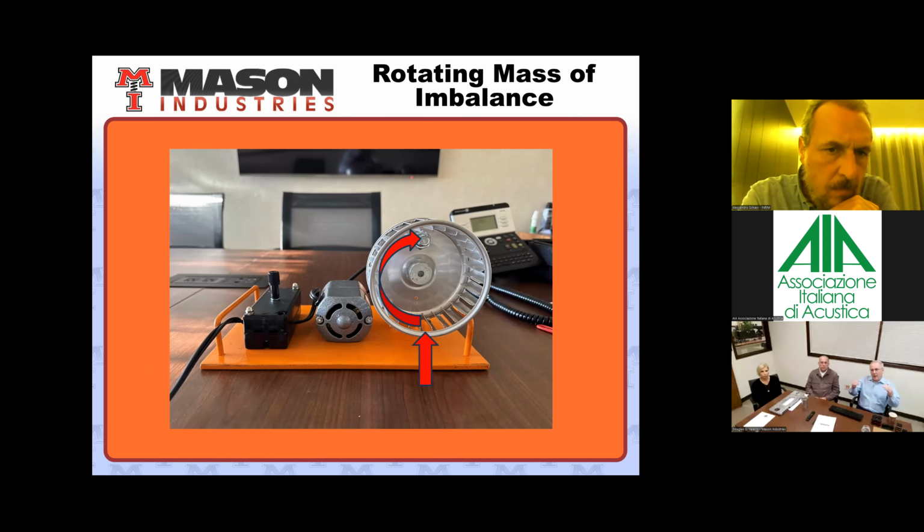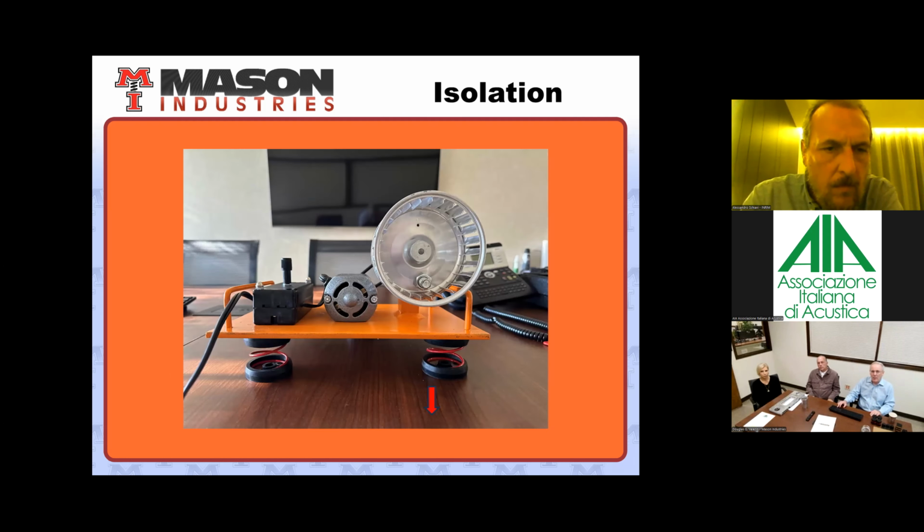And that up, down force creates vibration, which can be aggravating in its own right. But more commonly, that vibration will radiate to an architectural element and create airborne noise. Okay, so what we want to try to do is isolate that equipment to reduce the vibration force reaching the structure.